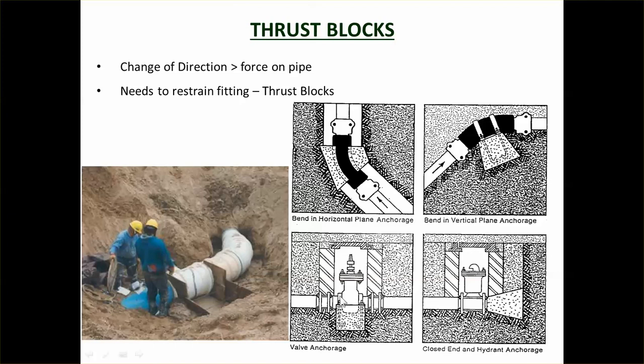Likewise, when you've got a gate valve, when you close the valve, the water is actually trying to push the gate valve over there. When you've got a terminal end where it's not going any further, once again the water is trying to push the pipeline apart.